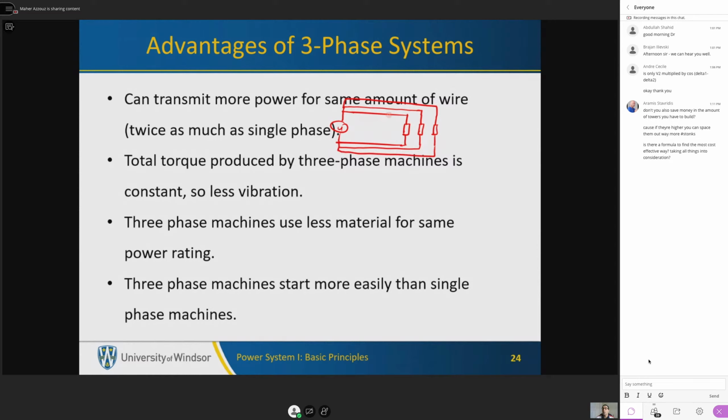So in total, we need 6 small wires, or 2 large wires. You can have a cable of this cross-section area or a larger cable to accommodate the 3 loads. I'm talking about 3 times 2, of course, because we have a returning wire, or we have 2 big cables to serve these 6 loads.